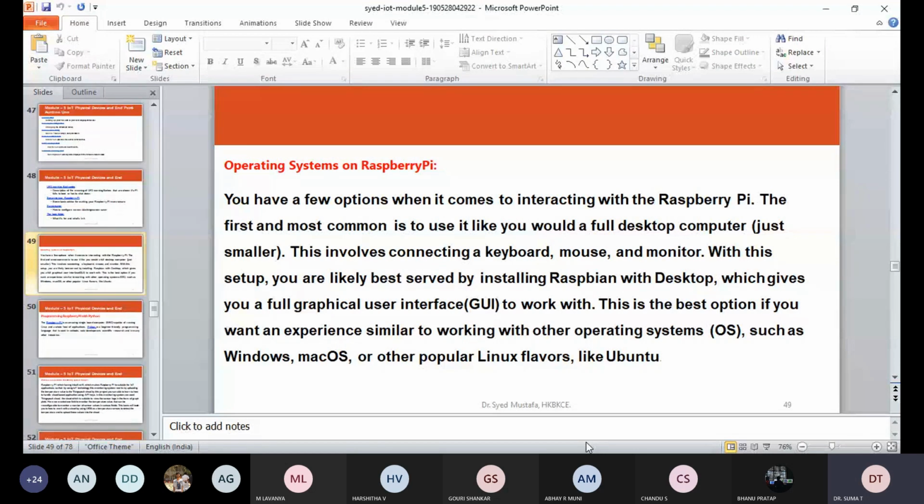To set up an operating system, we need an SD card with minimum capacity of 8 GB. Okay. So when we are going to format the SD card, care should be taken before copying the NOOBS onto it. So download SD Formatter 4.0 from the SD Association website for either Windows or Mac. Follow the instructions to install the software. Insert the SD card into the computer or laptop SD card reader and make a note of the drive letter allocated to it. In SD Card Formatter, select the drive letter the SD card is in and format it.